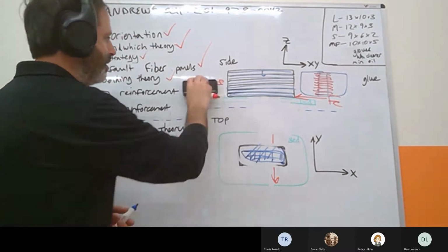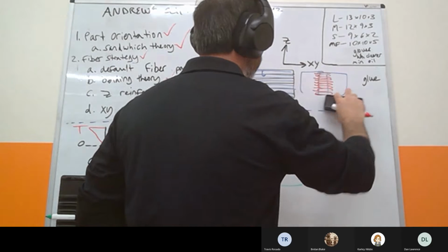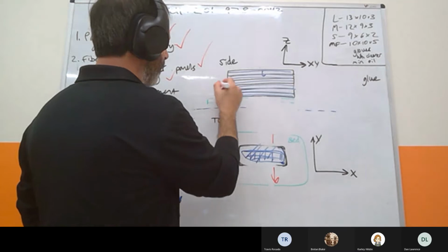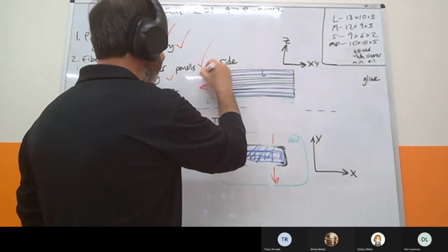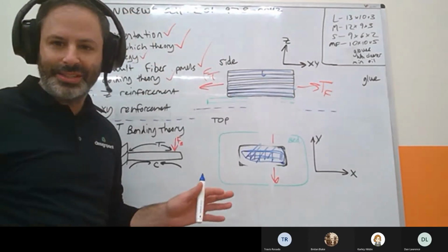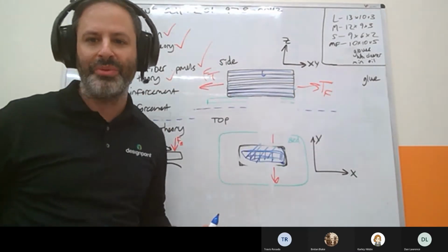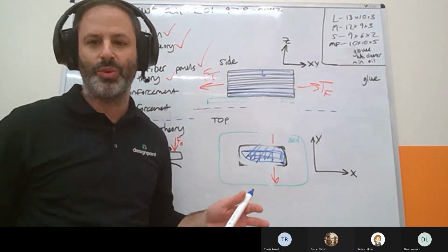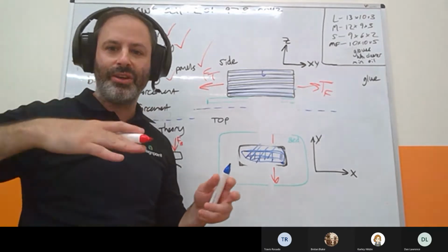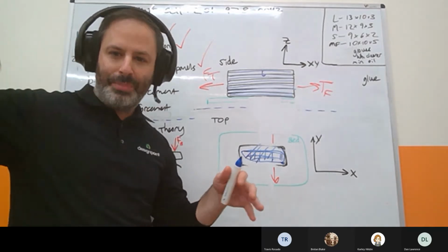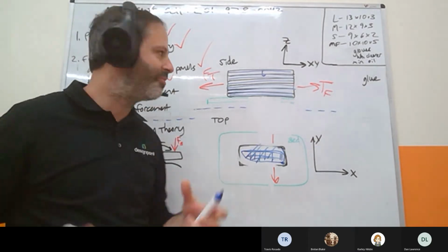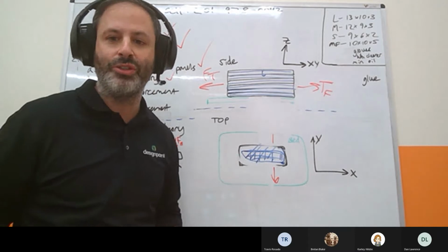Now let's look at tension versus fiber. All right, well, tensile force from the side. This is very similar to what we were talking about before, but it's the same story. This is your absolute most ideal scenario. If you can align your tensile force in the XY and put down fiber, specifically perimeter fiber, to prevent it from pulling out, you're going to get very, very good strength off that part.